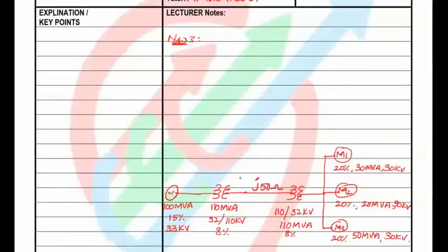So for this network, this is transformer 2. Okay, so here its voltage is 110 kV, which is the base value, right? So now I'll write the formula. XT primary side is equal to 0.08 into MVA new, which is 100 only, divided by the base value. What's the base value here? What we found is 113.43 here. It's the primary side base. So 113.43 whole square, and you will get 0.0684 per unit, the same as before.